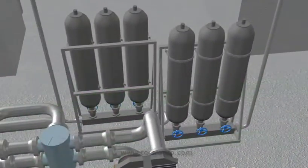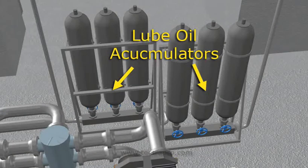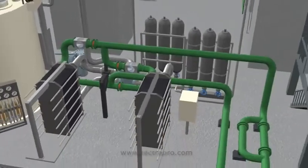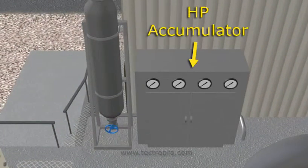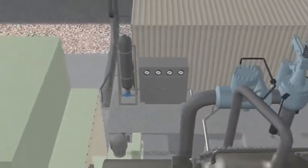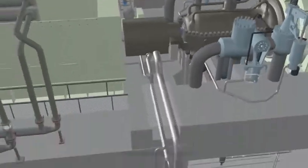The lube oil accumulators help dampen any pressure surges in the oil supply to the journal bearings and 1 thrust bearing in the turbine generator package. The high-pressure accumulator dampens any pressure surges of the oil going to the main stop valves or governing valve servos.